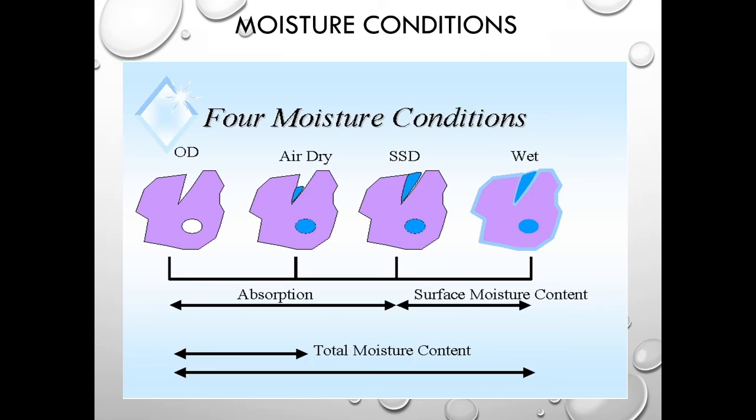We've been discussing water demand for concrete based on the aggregates, whether they're sharp and angular or whether they're rounded, and how they will influence the amount of water that will be needed for the mix. Moisture conditions of the aggregate are very important. The absorption and also the surface moisture of the aggregates have to be determined so that the total water content of the concrete can be controlled and correct batch quantities determined when we're batching concrete.